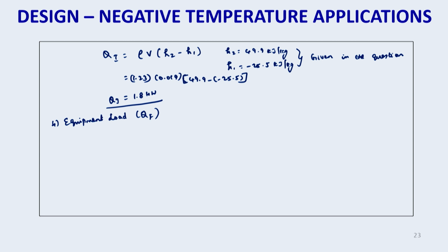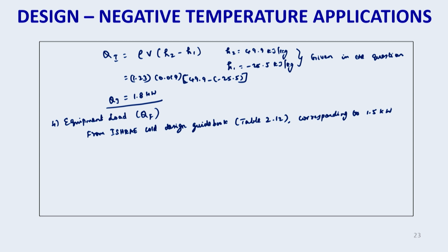Before that, let us take the value of the connected load in refrigerated space from the table, from the ISHRAE cold storage design guidebook, table 2.12, corresponding to 1.5 kilowatt. This 1.5 kilowatt power rating is given in the question.